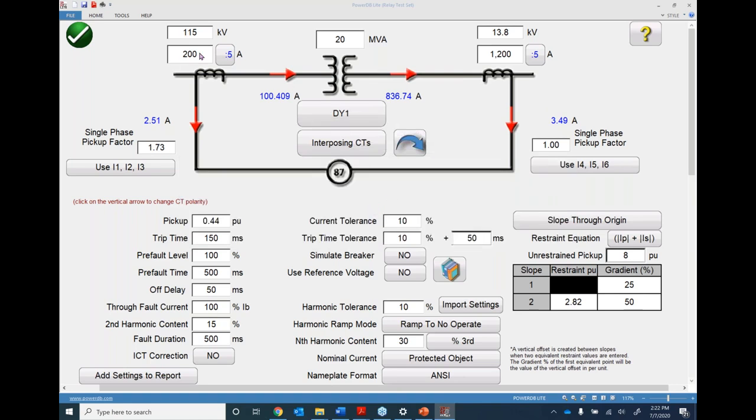So depending on all these values, the screen calculates these primary values on the transformer windings and also the secondary values, which are the taps. You can always verify these values from the relay settings, which show you the actual tap, wherein you can verify these tap numbers with the setting tap numbers to make sure that the values you entered are correct.